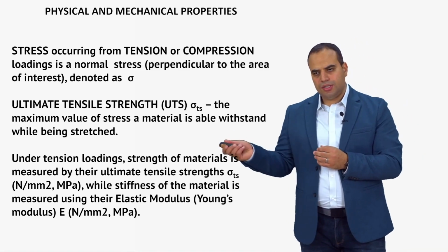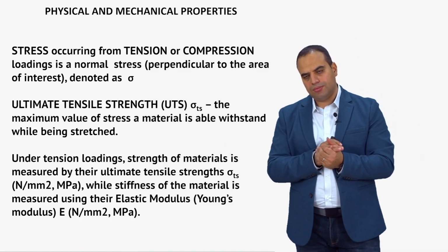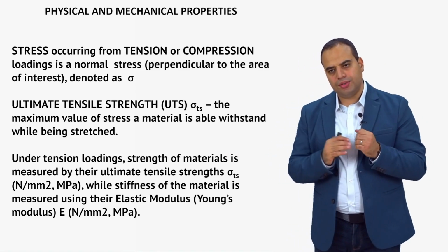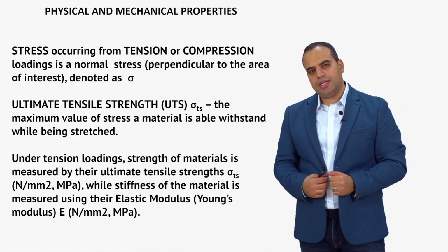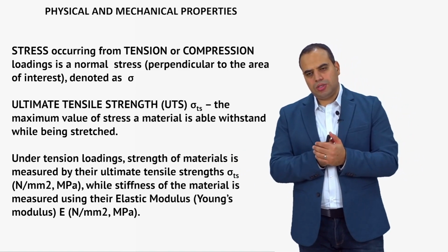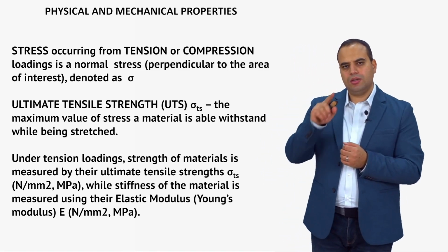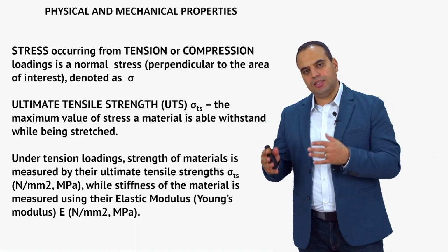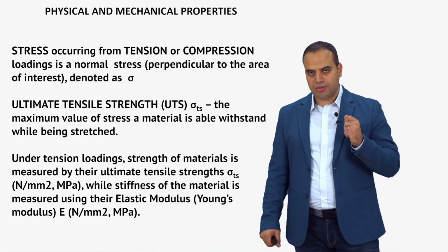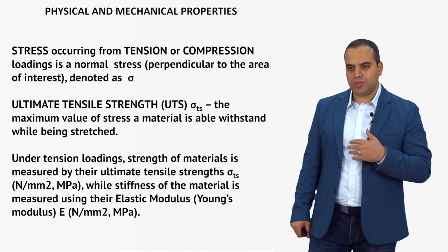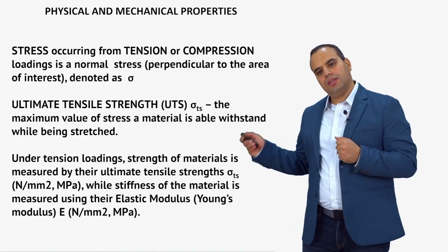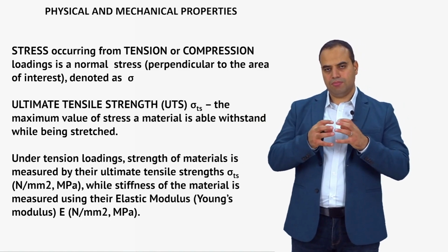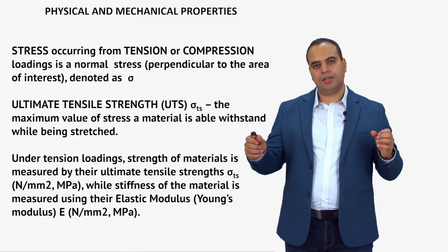And stiffness here also, which is I suppose the last notion that we have to discuss here. It is measured by the elastic modulus, or the Young's modulus, which is denoted as the big E. So it says how stiff the material is. So if strength talks about the ability to withstand loads without destruction, without losing the strength, without failure, while the stiffness talks about taking the load without deformation, right? So maintaining the form, maintaining the shape.